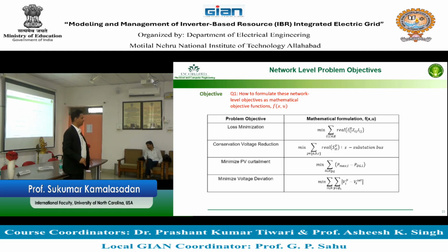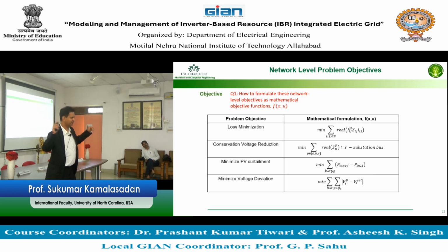Because at the end of the day, you want to reduce the power coming from the transmission network to the electric distribution feeder. If you reduce that power, you will reduce the cost. So to operate an electric distribution feeder, what will be the power on the substation bus is what you are trying to find out. After you do that, you will get the required voltages for the LTC on the source side. So you can tap and make sure all the voltages on this can be met.